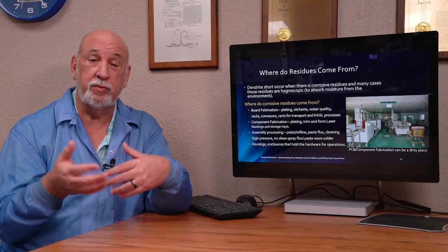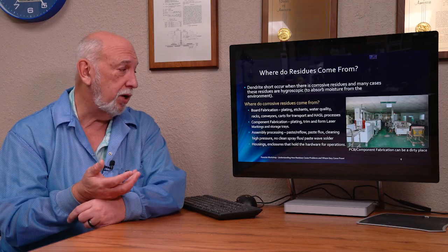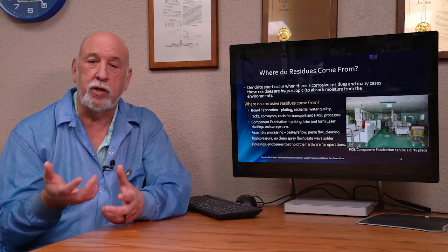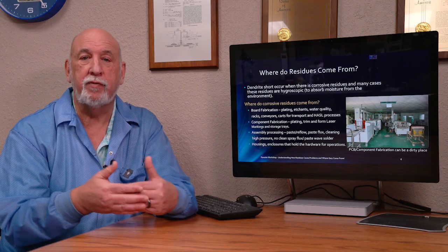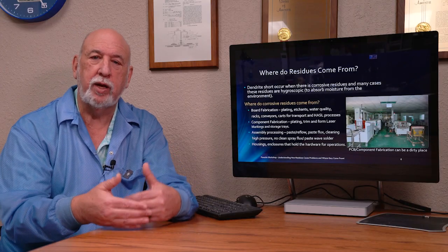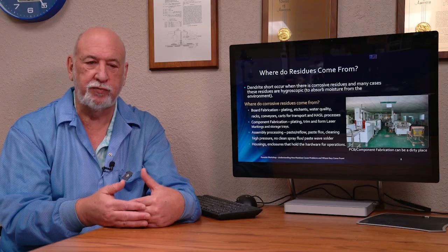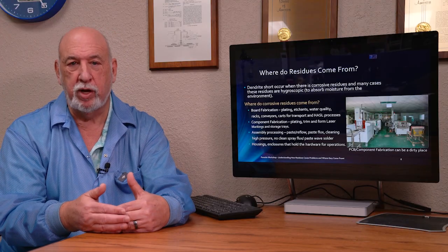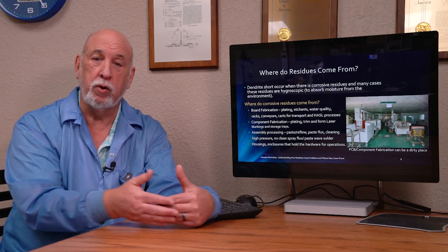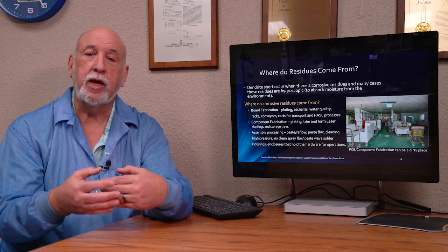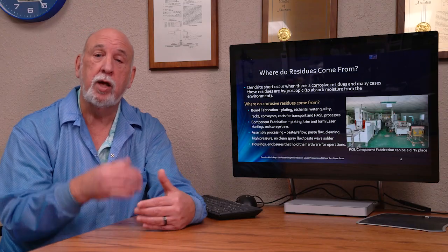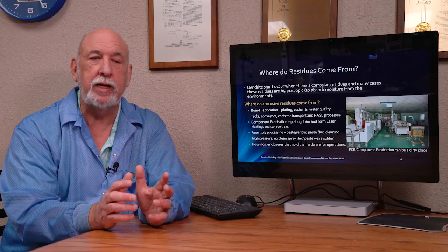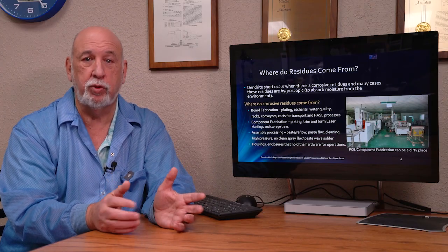Then we go to assembly and look at the assembly processes, how those interact with the fluxes. And since about 80% of the industry is no clean, we have those variables all being a cumulative effect. Now we've got a surface mount process and a selective soldering process, a hand touch-up and repair or rework process, all of those introducing more levels of contamination. And in some cases, we're using a brush and some isopropyl alcohol to spot clean an area. Those areas create additional contaminants that are very moisture absorbing and very corrosive.